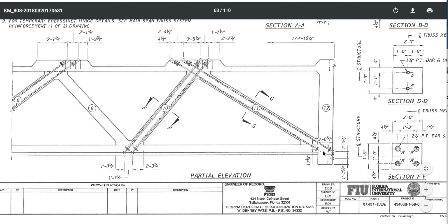It's sagging down. The clamp force is lost in number 11B, and this will be 11A. It's lost. It allows it to lift up into the air like that. And then it came to a stop. Why did it come to a stop and not go to the ground? Because they only loosened tension number 11, and then it popped, cracked like hell.